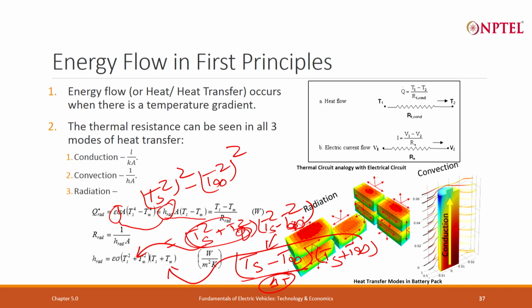And radiation does not need any medium. I am radiating to you, you are radiating to me. Net, because of the temperature differential, whatever net heat transfer is happening could increase or decrease the temperature of this room. Even I am radiating to the wall, and the wall is radiating to me. So radiation is always present. However, at a lower temperature difference, it is not very significant.